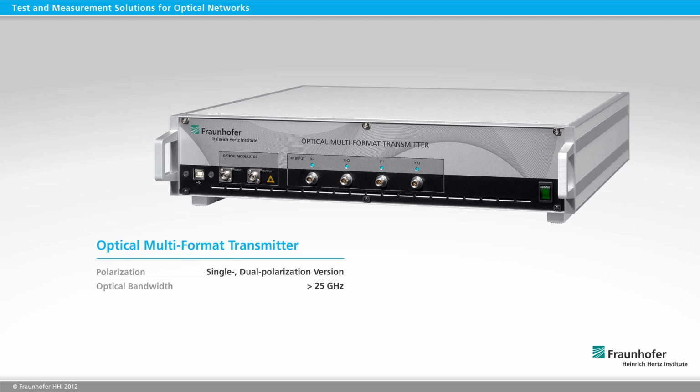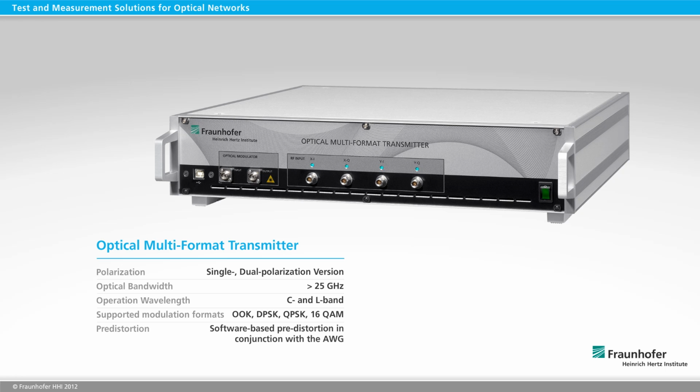more than 25 GHz, C-band and L-band carrier frequencies, support for numerous modulation formats: On-off keying, DPSK, QPSK, 16 QAM. Software-based predistortion in conjunction with the AWG.